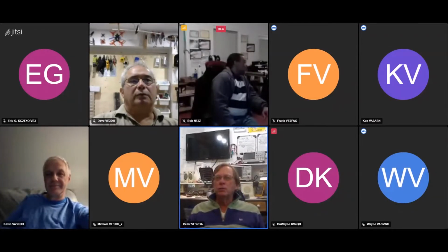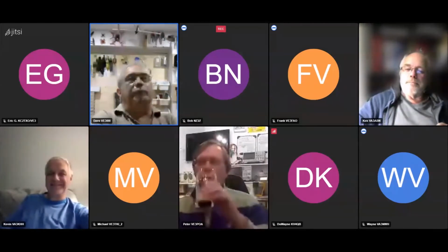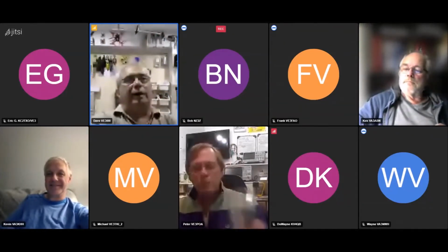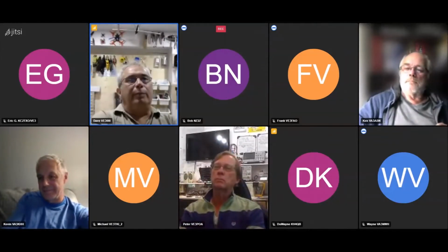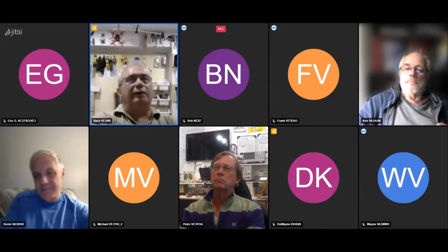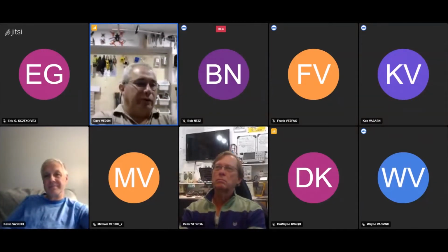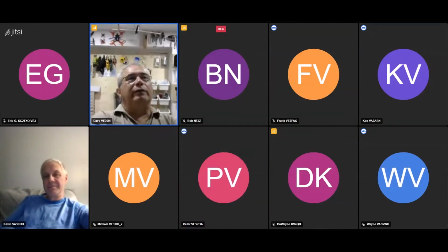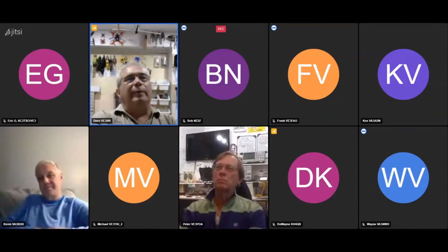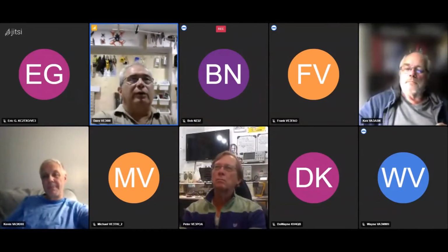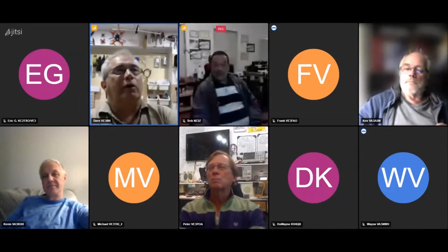Maybe I read too much, not enough doing. Yeah, Peter, there's a really good video I came across, because in light of what I'm doing with this board and all the coupling, I'm getting all the parasitics. So I started to look at PCB design, and there's a video where the guy has the five most common mistakes someone makes when they make a PCB, and trace width was one of them. He said using the wrong trace width, because he said it's kind of interesting.